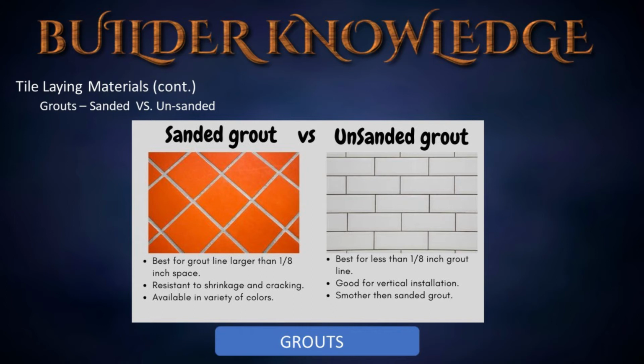I wanted to add a little information for you that Petty Officer Google sent me. There are two main differences in grout, and as you can see, it is sanded or unsanded. If you are placing small tile or large tile with little space in between tiles, you must use unsanded, or you will possibly scratch your tile, trying to force the sanded grout where it can't go.